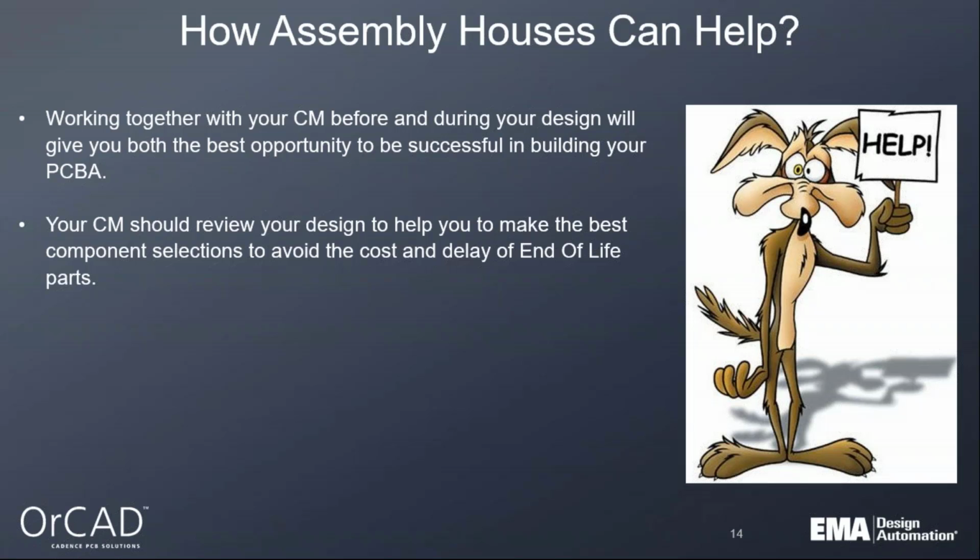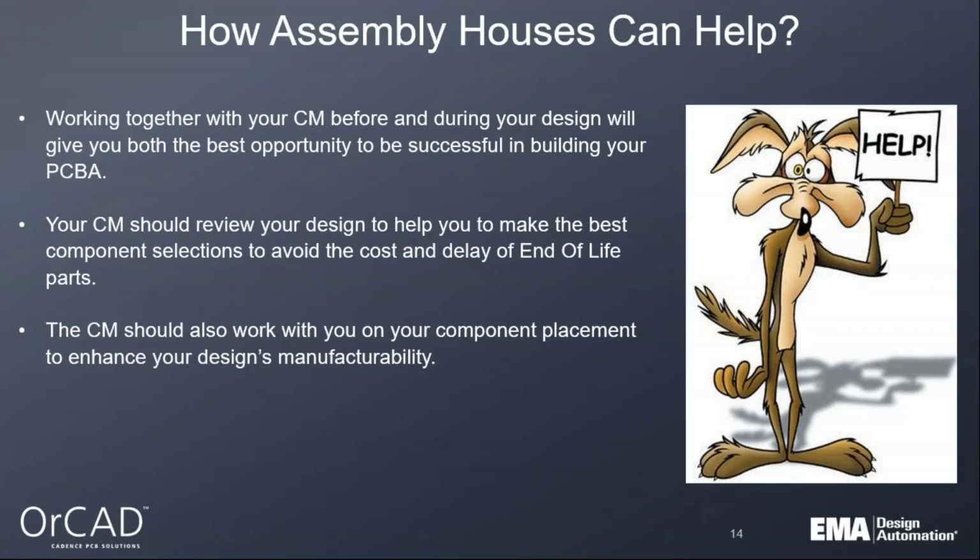When I'm designing my boards, I often send them to whoever the contract manufacturer is, so that they can look at the placement before I start routing and get an idea of what's going on with my design, so that they can help me out. Maybe I have to move some components. Maybe I have components that are too close to the edge of the board. So it's important to work with your contract manufacturers while you're designing that board.